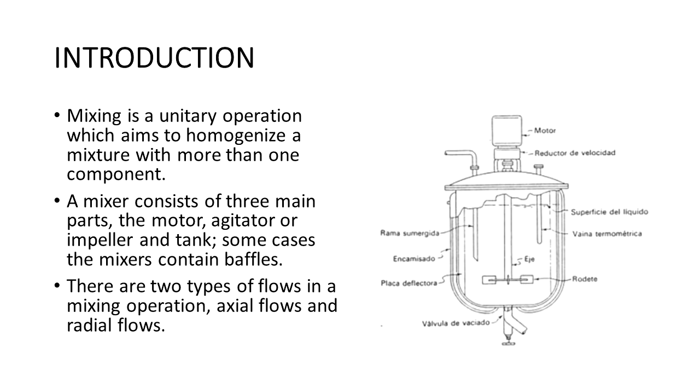Axial flow is generally used for suspended solids as it tends to have an effective top-to-bottom flow pattern and generates a homogeneous mix throughout the tank. Radial flow tends to form two different mixing zones in the tank, on the top of the impeller and below the impeller.